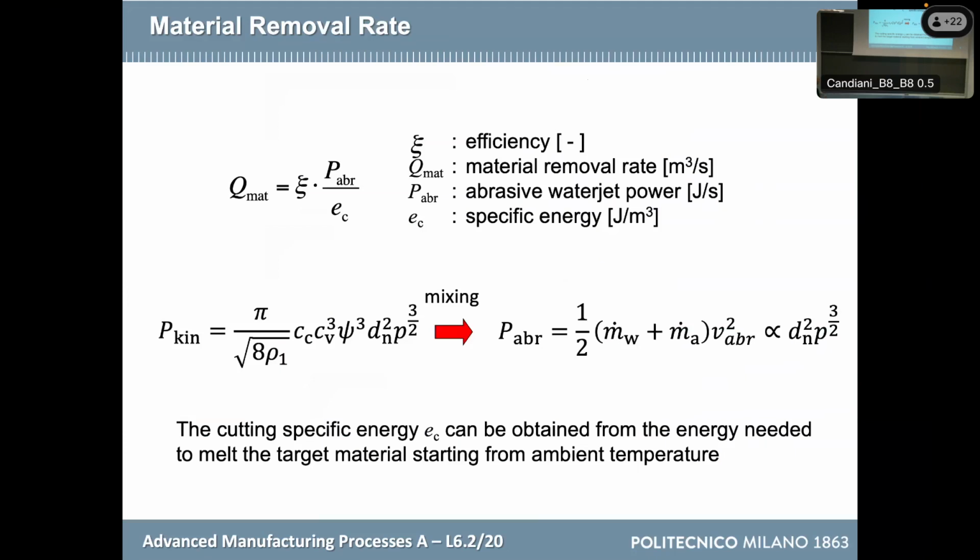If you think about this equation, it is absolutely equal to something that we have already seen in chip removal processes, where EC is exactly the same as another quantity that was representative of that process, which is KC. And in fact, this equation is really helpful because it allows us to compare processes.